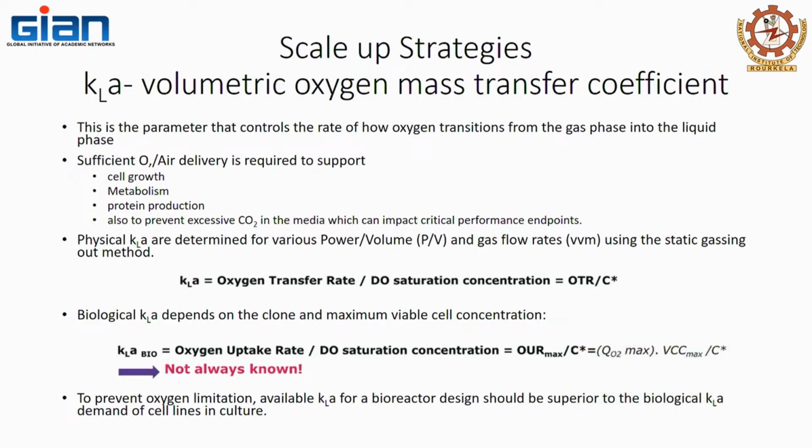The other scale up strategy comes for the KLa. So, she was right, you have KLa, tip speed, power density. I am going to put you in place, do not worry about that. So, tip speed, power density, KLa. KLa is for the aeration. Now, tip speed, power density is mostly for the agitation or the design of the geometry. Tip speed is with respect to geometry also. Power density is with the impeller, the agitation purpose. KLa is with respect to the oxygen mass transfer coefficient.